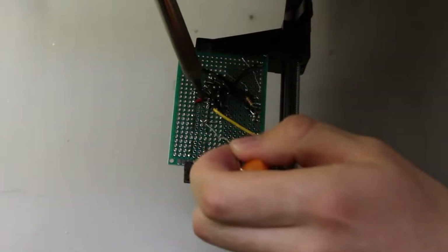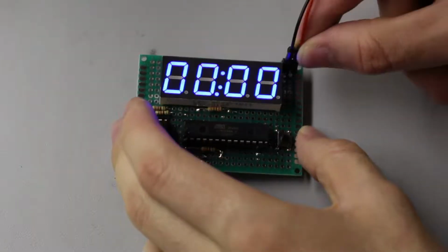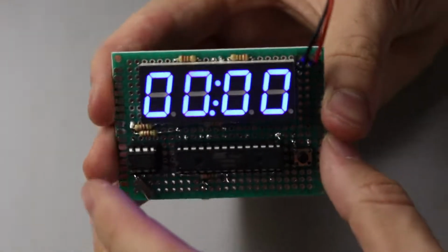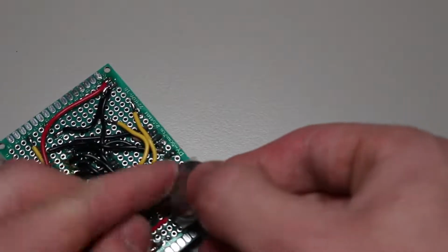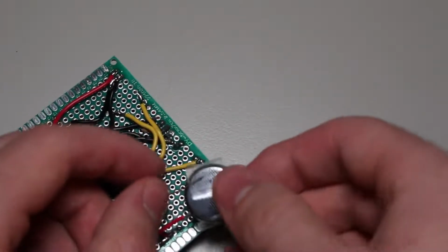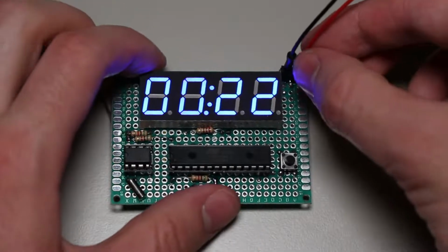After some time soldering, this project is mostly complete, and we can see that it works mostly as expected, except for one thing. I added a coin battery to the VBAT pin on the RTC, and now it works as expected, and the clock remembers what time it is even when we unplug it.